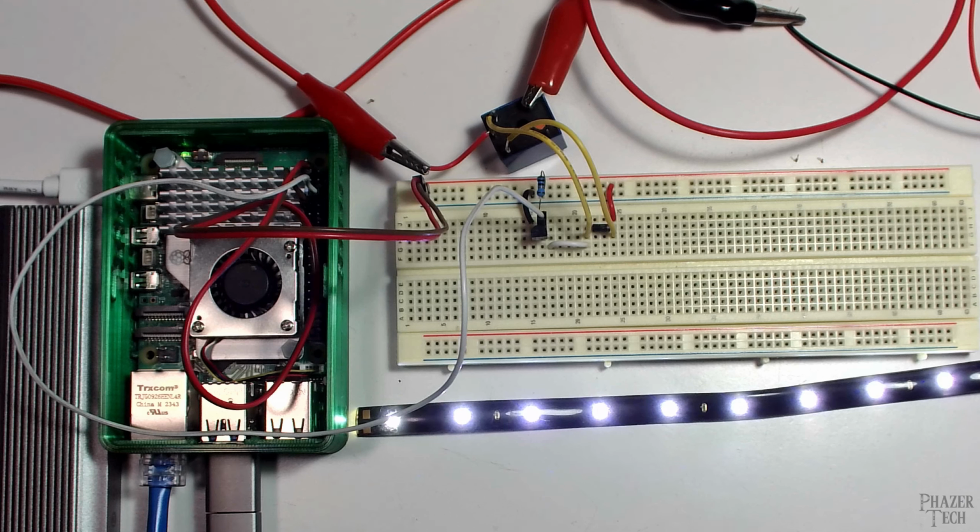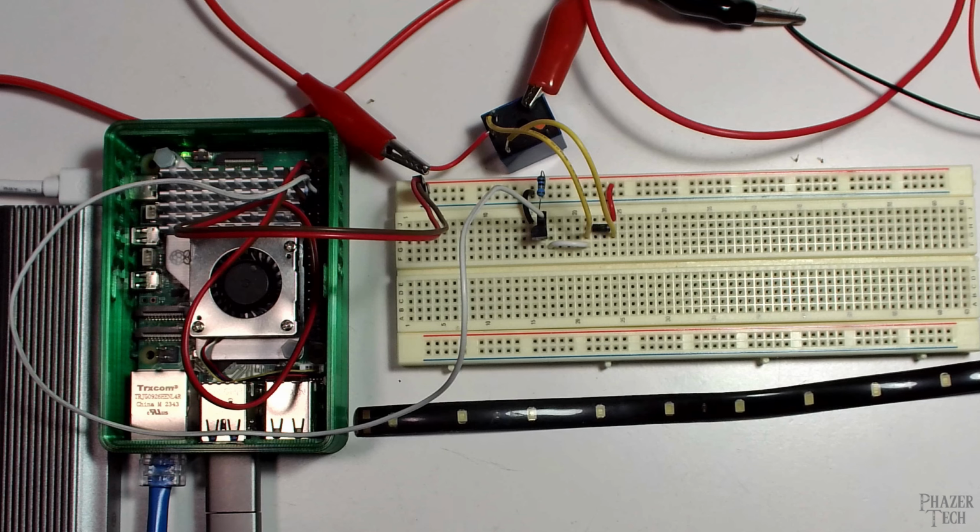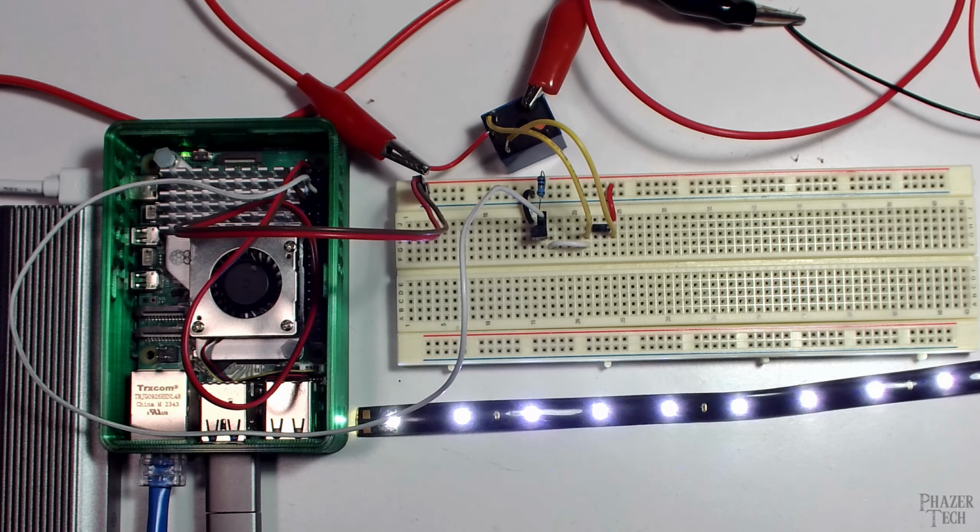I'm not sure if you can hear it or not, but every time the relay turns on or off, it also makes a clicking noise. So you actually don't need to connect an LED or anything to verify that it's working, since you can hear the switch clicking inside. And that's really all there is to it. Controlling a relay is really just a matter of controlling a transistor which activates the relay's coil.